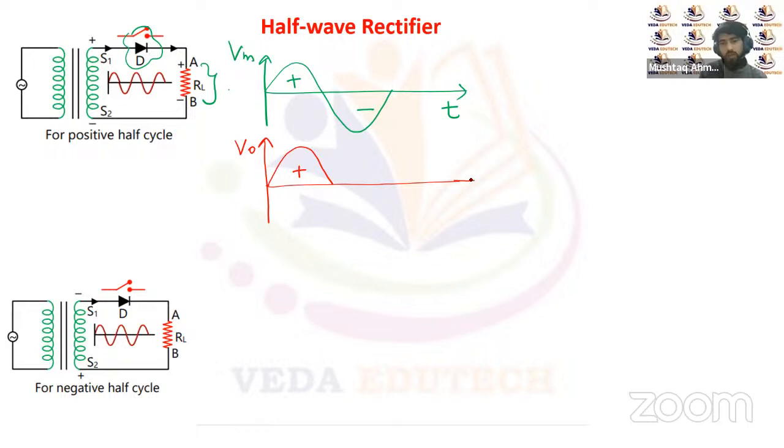Talking about the negative half cycle, you can see here that the P type will become negative potential and the N type will become positive potential, or we can say the diode will be in the off state. In the forward condition, the diode will be in the on state and conduct, but in the reverse biasing condition, it will be in the off state. So there is an on state for this diode, and an off state for this diode.